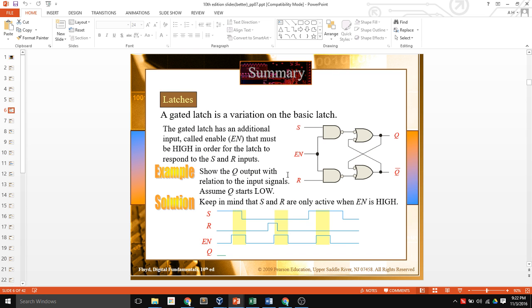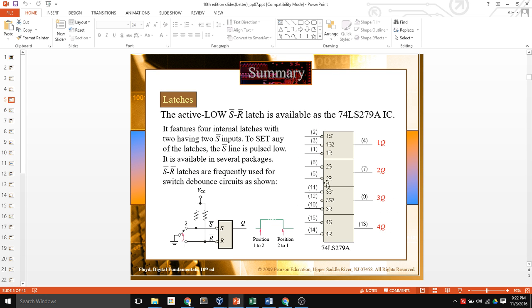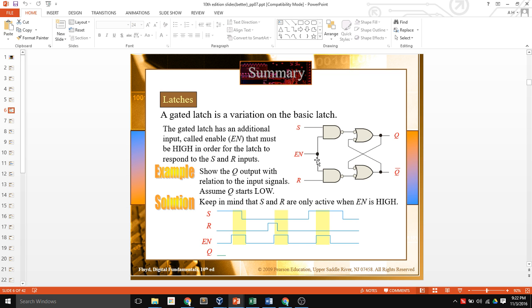And we've got the same kind of thing here. You can see we've got just a block to show it in the schematic. Here we have the exact same thing, but if you would remember, two inverters cancel each other out. So this is an inverter here, an inverter there. If I take this inverter on this side and stick it over here, then that turns this into a NOR